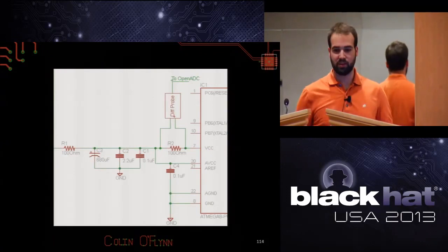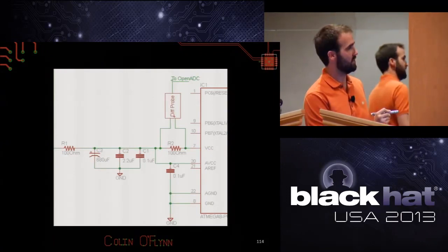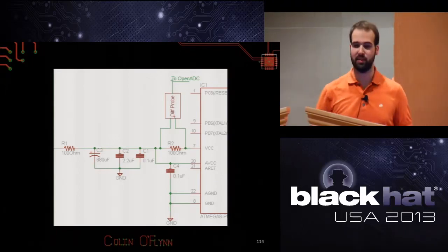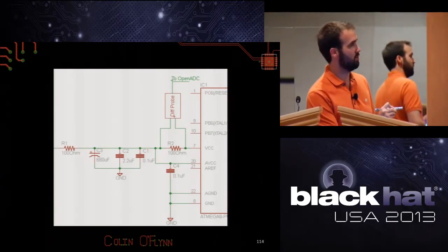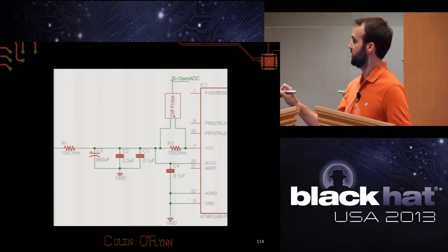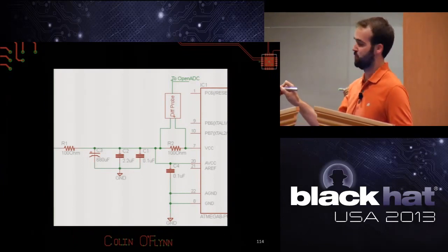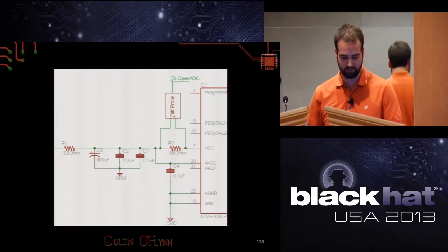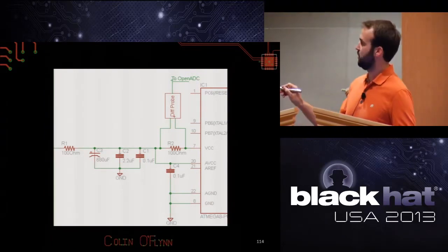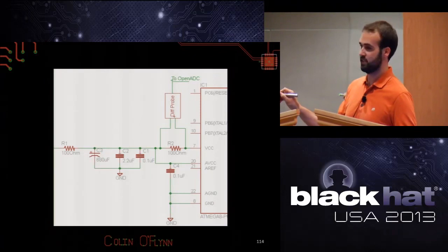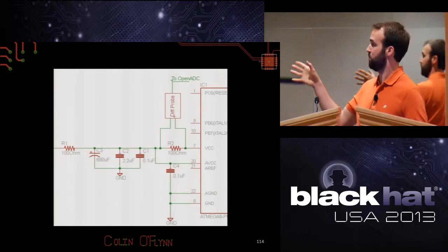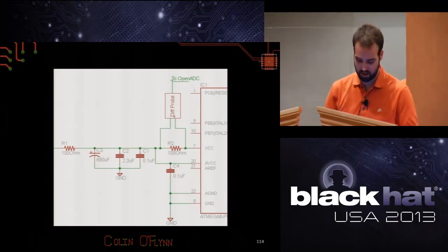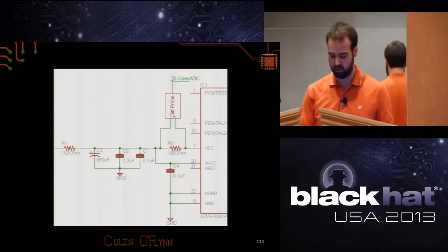So instead what we use is what's called a differential probe. All this does is you can see how there's a probe here and it's connected on each side of the resistor, that shunt I'm measuring with. The noise in the system tends to be coupled onto both sides of that resistor. So the noise coming through this line will more or less be coupled evenly to both sides. There's a tiny bit of variation, but we don't care. Now, this probe is only measuring the difference between the two sides of the resistor. So the noise that's common is irrelevant to the measurement then. So this is a really easy way to obliterate that noise problem.